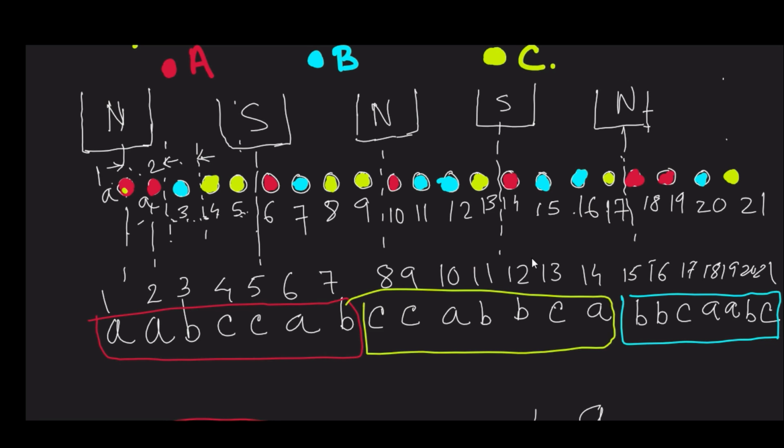So now you can see that on an average you are having 4 or 5 under each pole. So we got this distribution, and it is very easy to understand how for this fractional slot we can use the index number, and this can be done. This same distribution will help us to design an 84 slot 20 pole machine, or whatever be the case, we can draw it, right?